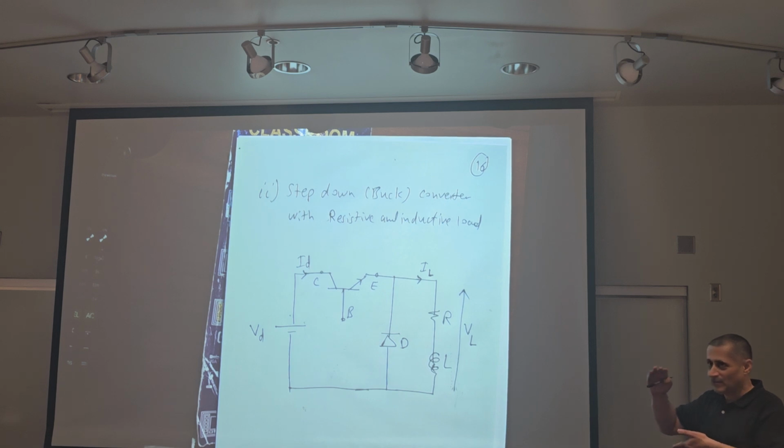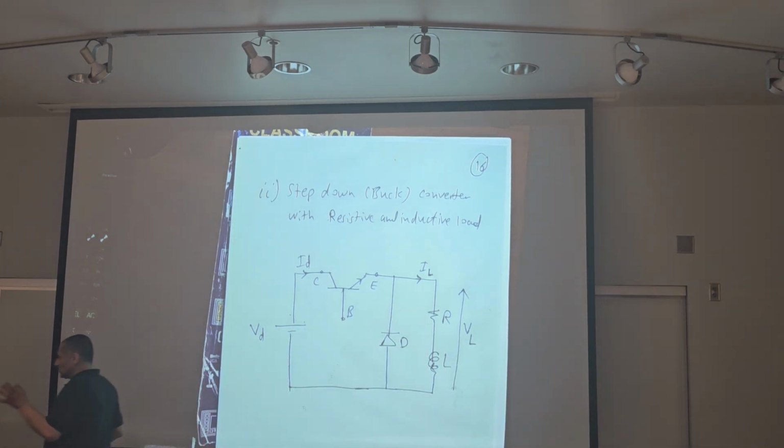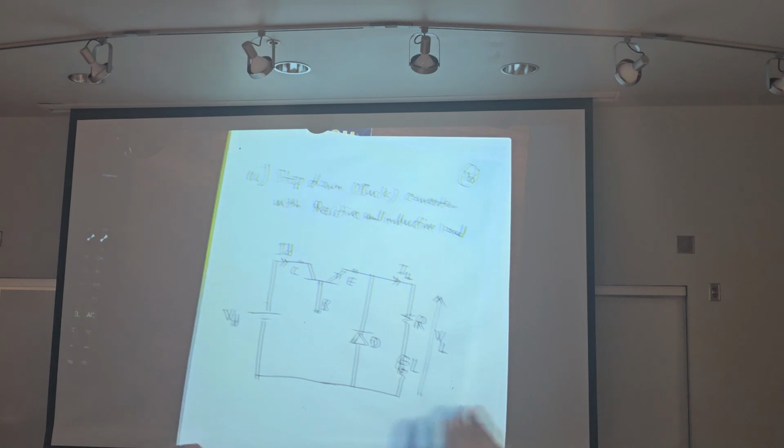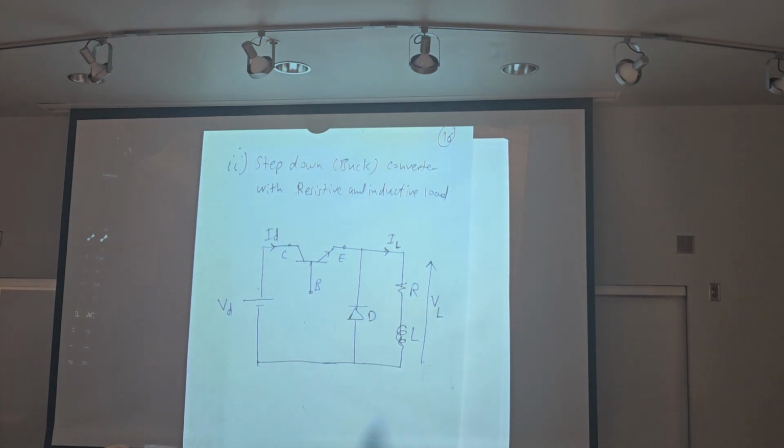The time is for the solution and design, not for deriving V DC, V R. No need to do any derivative for the equation. Just draw the circuit diagram, then write the formula directly: power in, power out, efficiency, V DC, V RMS, I DC.